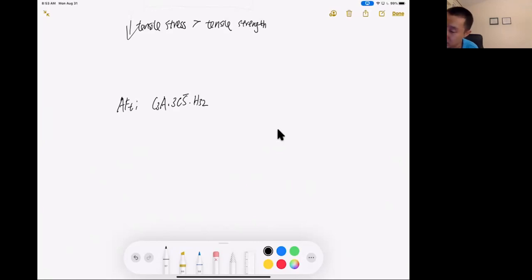So A is for alumina and F is for ferric. T is actually short for tri, or 3. So that basically tells us for 1 part of C3A, sometimes we have alumina or ferric interchanging with C3A. We have 3 parts of gypsum or 3 parts of sulfate involved with it. So that's where the name AFT comes from.